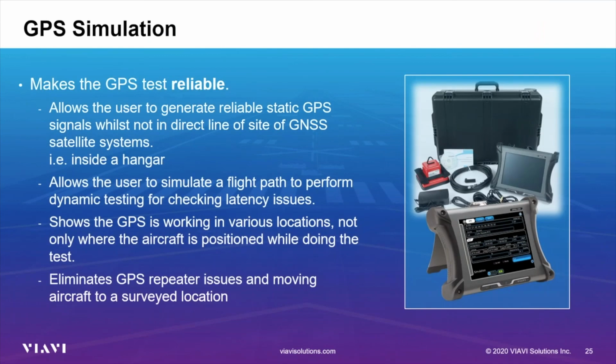So when it comes to GPS simulation, how does that ensure a reliable test? Well, the first thing is it allows a user to generate a reliable static GPS signal whilst not in direct line of sight of the satellite systems, i.e. inside the hangar.